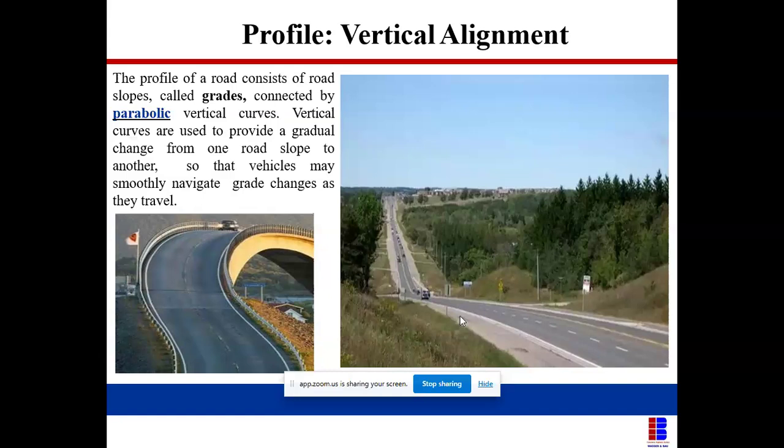As well, for a crest vertical curve and a sag curve, the design speed controls it. There's what we call the K value, the length of curve. You have the minimum K value for 50 km per hour using a 6% superelevation, and 100 km per hour using 8% superelevation. Those things will be shown when we're using the software. You see them based on the AASHTO standard, which the Federal Highway Manual was derived from. So we have those K values. Those K values control what we call our passing and our stopping sight distance as well.